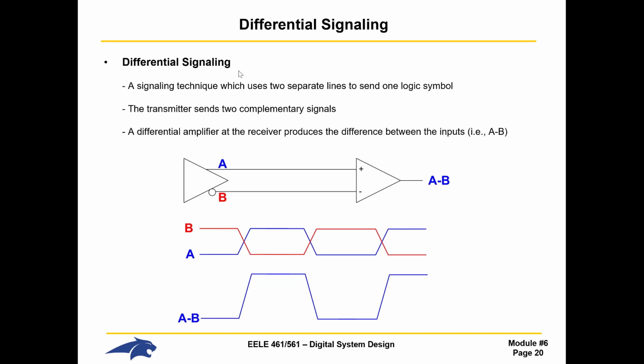I will tell you right now, when a neighbor comes along and gets too close to you, if it's held at 0, it causes your impedance to change. And the solution to that, when you run what we call single-ended, which is where you're just sending one line per one bit of information, is just to space your neighbor out. So don't put traces too close together.